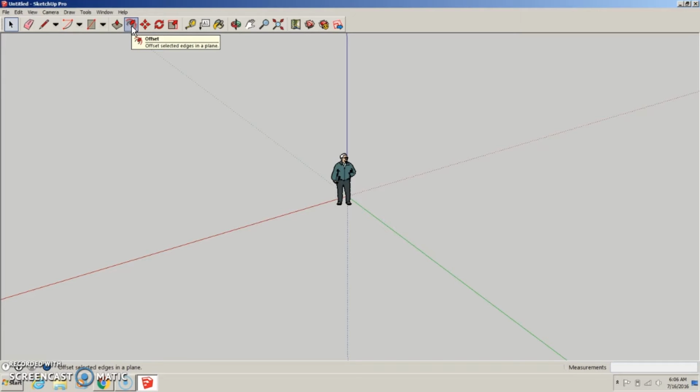This next tool is the offset tool. We'll make another surface. Select offset. The surface highlights, I hold down the left mouse, I drag inside, and it takes the outer boundary and helps me draw an offset, or at a certain distance from that boundary.